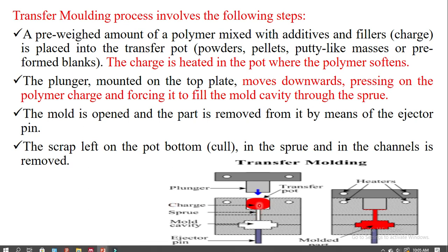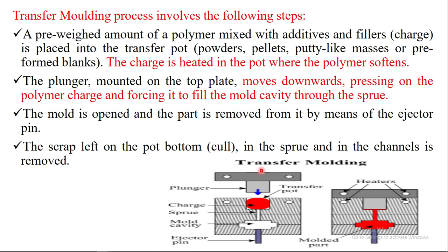See this one. This one is the charging process. Upper mold, lower mold. After the plastic materials are put on here, weighed, in here, mounted on the top plate. These ones. Then the top plates come here. This is closed and looks like this. After touching it, heat is applied on these products. Then after the heat is applied, this is converted into a liquid. Then the pressing process is done.